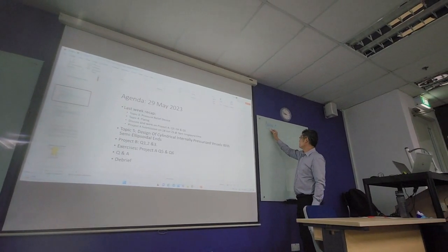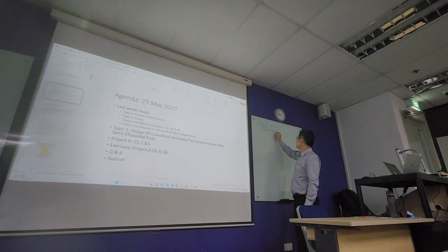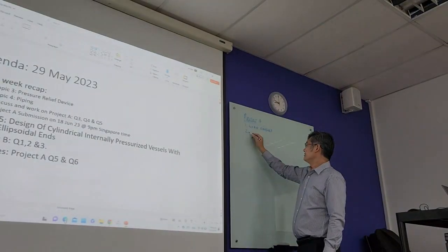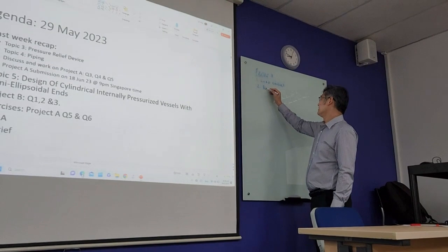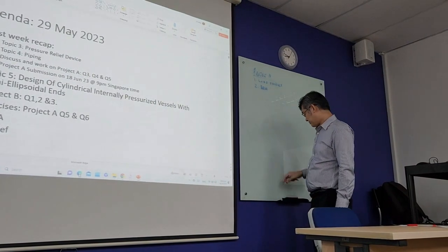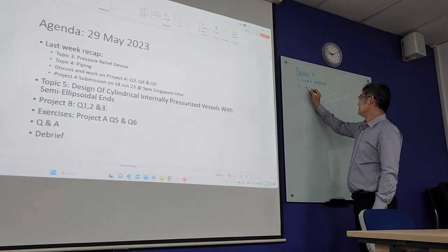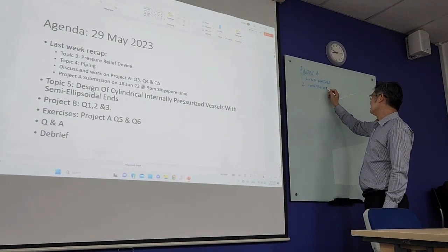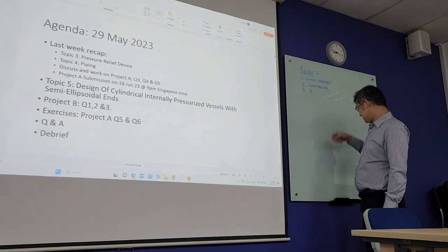First we find the load factor, with the force on and force off. Followed by the second question, we find the compressor selection. Followed by third will be your receiver and receiver size.